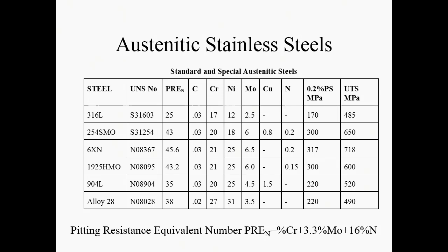In that sort of case, maybe a little bit lower, but they are within the range of what might be used in the industry. That means that if you want to use them, they tend to be thicker because they have to withstand the same pressures. And if they're thicker, you're buying more material, and if you're buying more material, they're even more expensive. So that's the reason why we try to avoid austenitic stainless steels unless we have to. But they are very widely used in industry, and there are good quality supplies available.